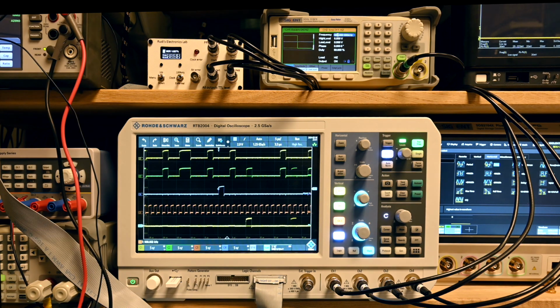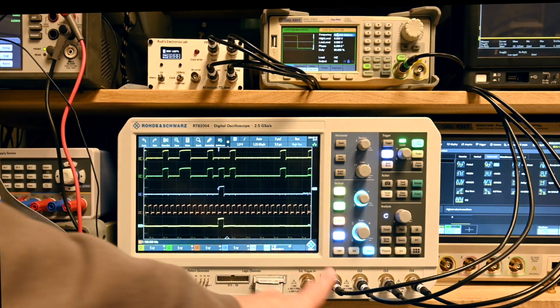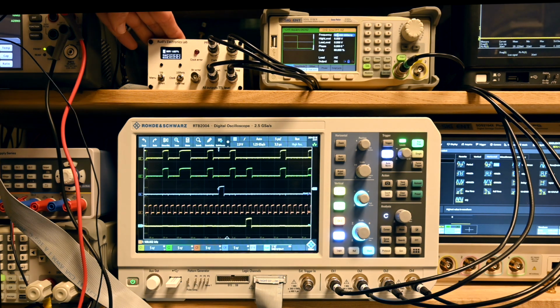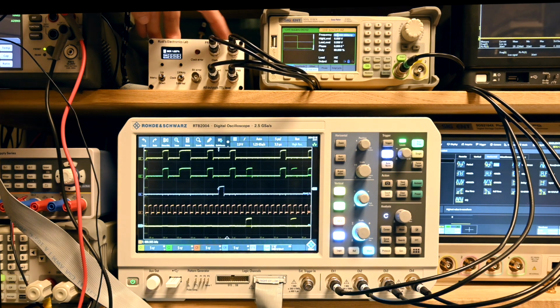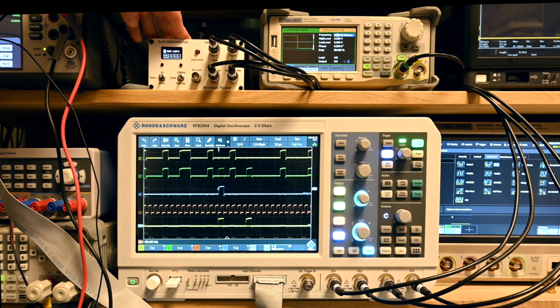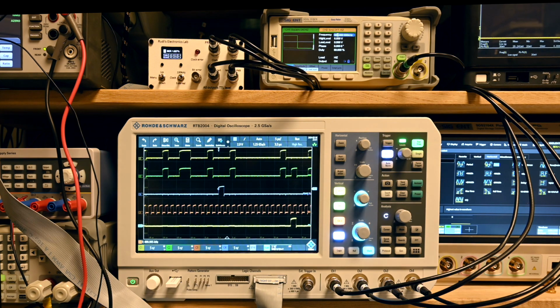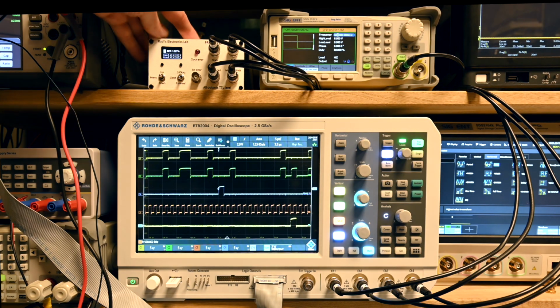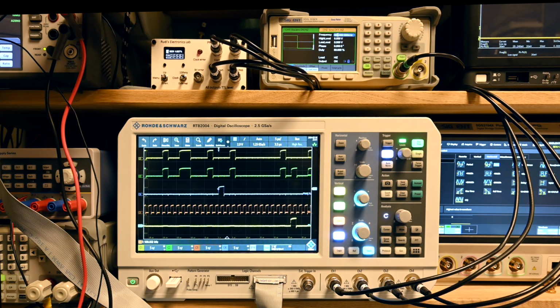Well, that's okay with TTL signals, and we just bring that into the scope without any specific impedance matching. Again, the reason why I'm using TTL signals is because the BER testers I want to try later on are TTL. I'm still thinking about adding some extra outputs here that are buffered and a nice 50 ohm output signal, so we can also use it with scopes a bit better. But it's not a big deal. The signal is clean enough as it is for this purpose. So now we're running on half a megahertz from the external source.